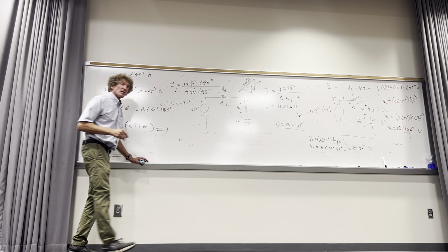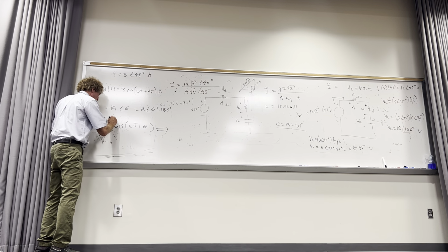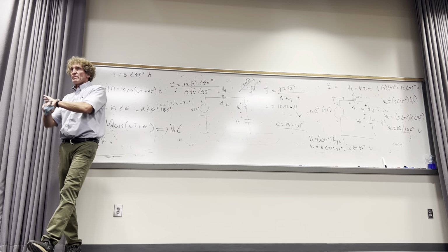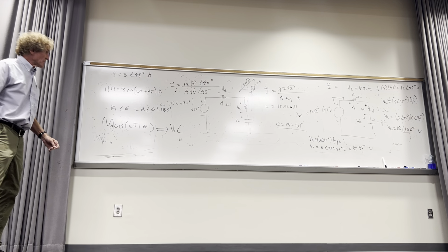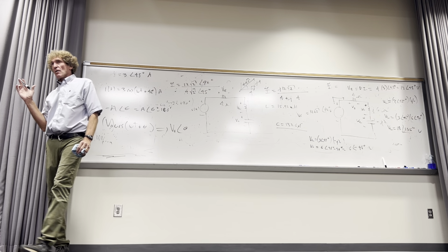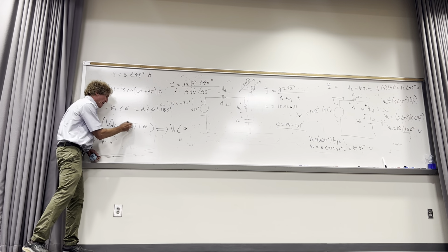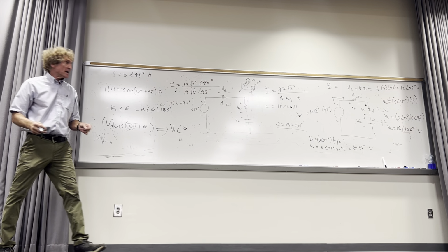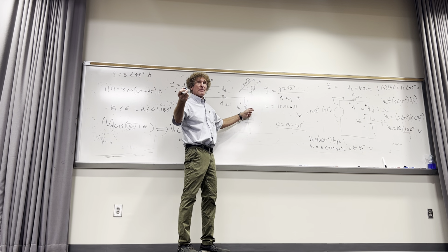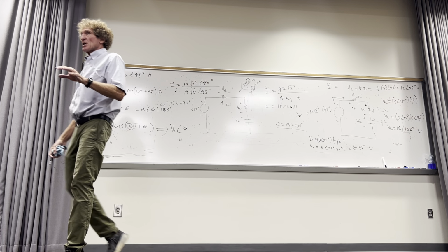To take that and go to the phasor domain, the magnitude V naught comes over. So you bring V naught, you eliminate the cosine of omega t. It's gone. The only thing you do is take that angle and put it right here. That's it. Now, the thing you have to get from this is the value of omega, because that value of omega is used to get the reactance, or impedance. It would be J omega L, or for the capacitor, minus J over omega C.